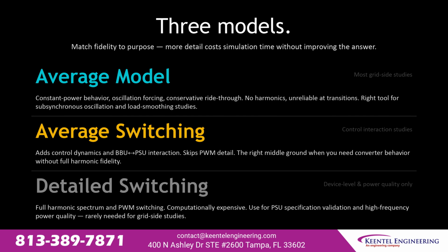Detailed switching gives you the full harmonic spectrum, and PWM switching. Computationally expensive. Use it for PSU specification validation and high-frequency power quality work. Rarely needed for grid-side studies. More detail costs simulation time without improving the answer. Match the model to the question.